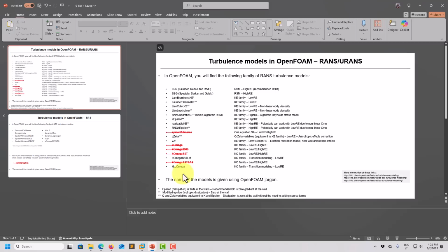So hopefully now you know how to properly set up this case. Be careful with the high rate, where I recommend to use the U-based wall function instead. For the low rate, you can use any of the variants. Personally speaking, the Spalding one will give the best results.